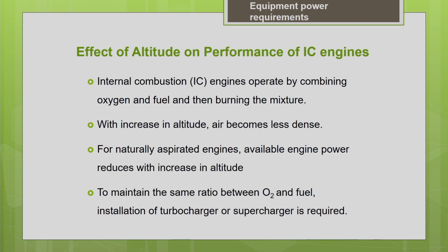As the altitude increases, if your project site is located at a higher altitude, the atmospheric pressure will be lesser and the density of air will be less. If you are not able to maintain the fuel to air ratio, then the combustion process won't be efficient. In that case, if the altitude is going to be higher, the efficiency of the machine will be affected. So you have to take into account how much the efficiency is going to be affected.